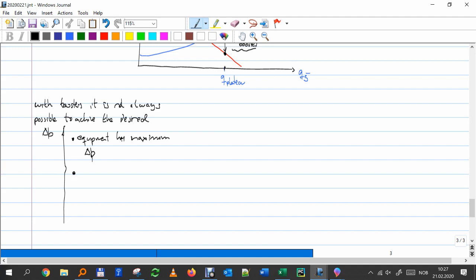The power, right? We know that if the delta P is too large or the rate is too high, I need to use more power. Okay, what is the power expression for pumps, for example? You remember? You have to dig back now. You saw it in school, the teacher told you, well, power of a pump, okay, is equal to rate times delta P, divided by the hydraulic efficiency.